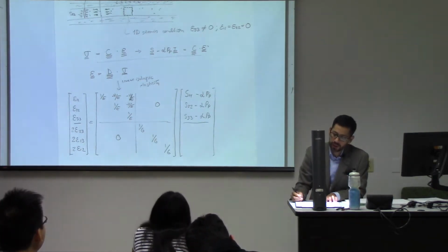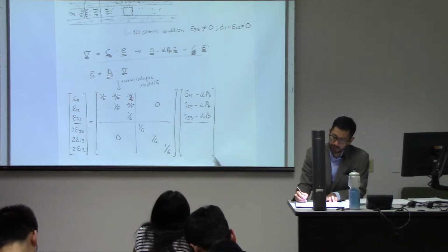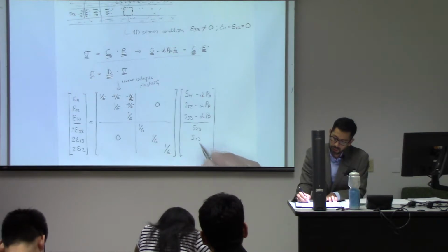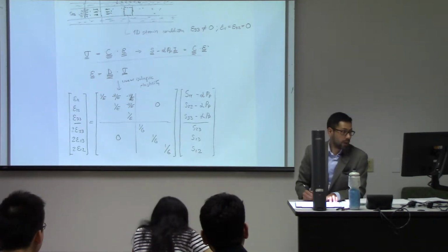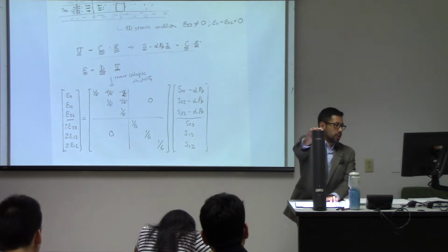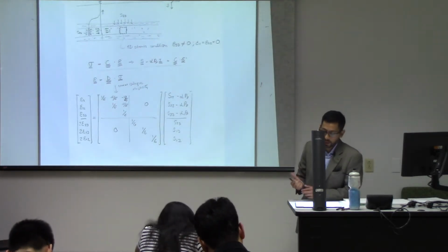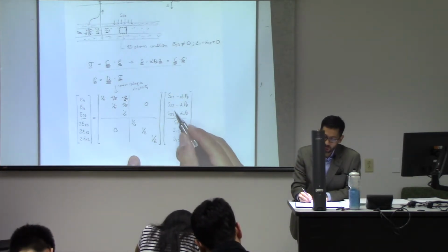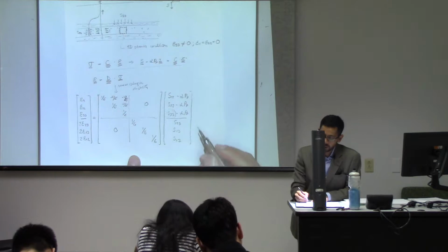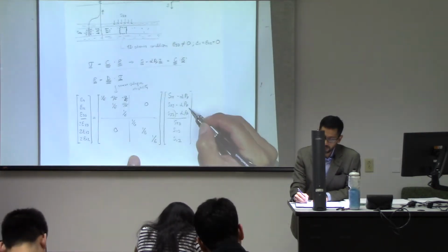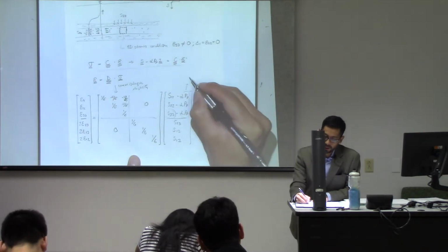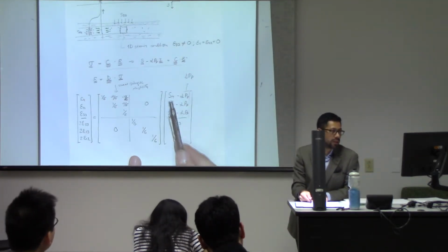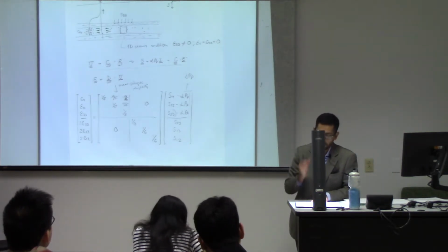What about the shear terms? Are they going to be affected by pore pressure? No, right? So I can just write this, S23, S13, and S12. Notice that in this case, what stays constant is the overburden. And what changes is the pore pressure, right? So there is going to be a change in pore pressure that is going to affect these two. These two are our unknowns.